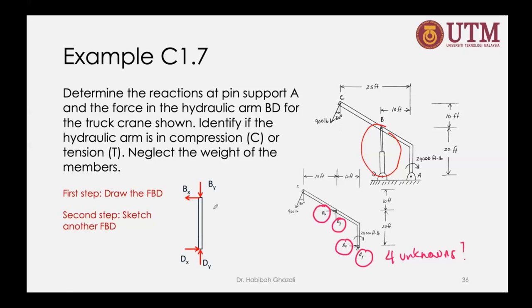You might find this very boring, that Dr. Biba keeps talking about supports again and again. But later in the exam, I will mark those who treat a pin support as a roller support, or a roller support as a pin support. Don't get confused with that, because with just that small mistake, the whole answer will be wrong as well.